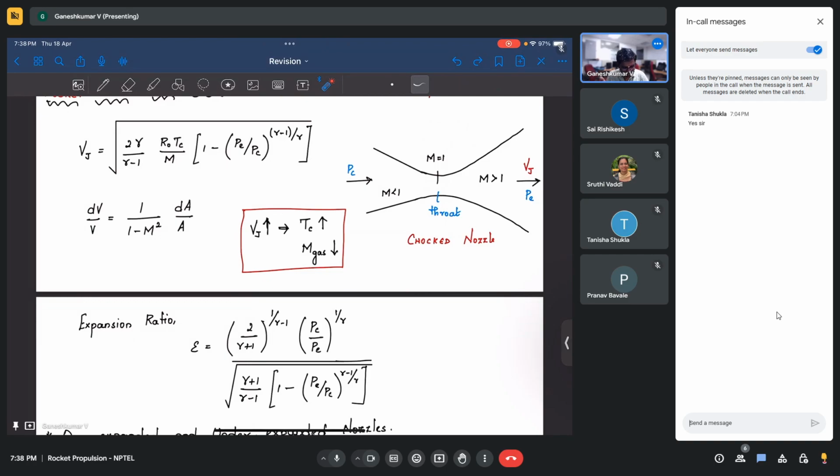within the flow. Let's say if I change something here in the exit, it will travel at the speed of sound c. Also, if I change something here, it will also travel with the speed of sound c. Now, since I am also traveling with speed of sound c, v is equal to c, the information will never reach me, because information will come at c and I will be traveling at c. The velocity here is c. So it will not have an idea that the contour is expanding after the throat. So it will keep on getting accelerated as you go down.